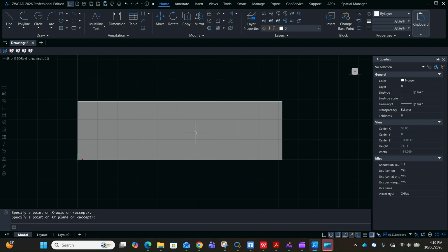Let's say I need to keep a gap of 13 from starting point. So I'm going to draw a polyline and then going to track, and tracking from 0, comma 0. Which direction? This direction, the value of 13. Then enter. Now I need to finish the tracking, then hit enter again. Now I'll go up and the value is gonna be 16. Enter.